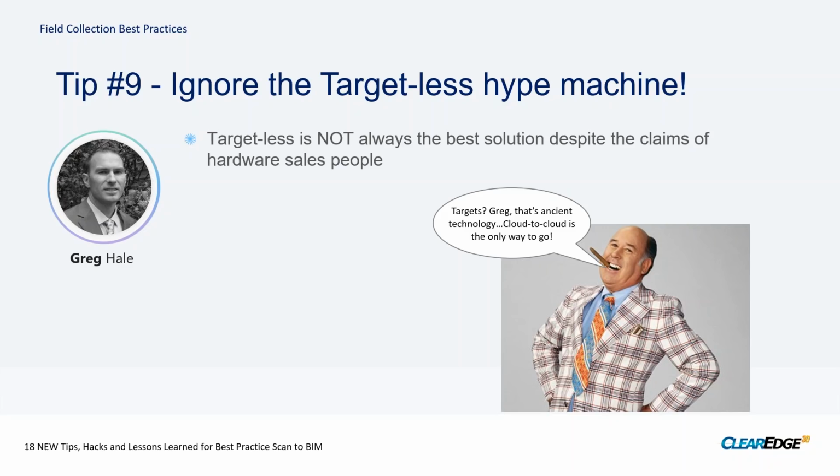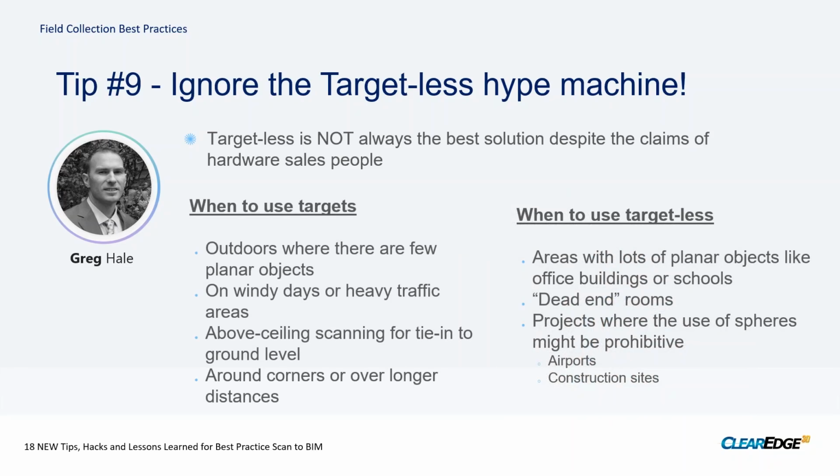Greg, you want to talk to us about that ancient technology called targets? I love it. Yes. So beware the salesman should be the other caption on the slide. Certainly a lot more people are coming into the idea of scanning, a lot more scanners being sold out there, some people who don't necessarily have the same kinds of backgrounds. So what I've seen a lot of lately is, just to get people's foot in the door, to get them to buy the scanner, basically overselling it and saying that you really don't need targets to provide a good, complete professional service. And so I've seen too many people caught in that trap.